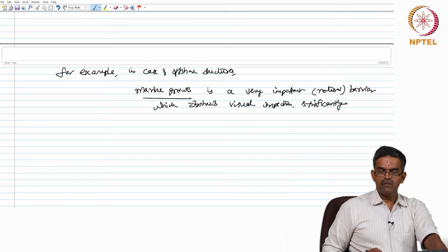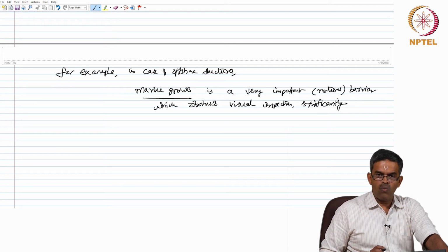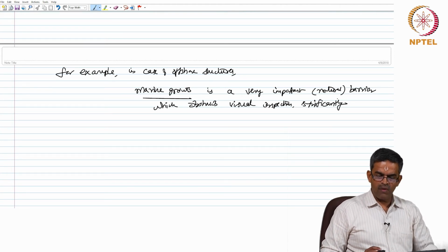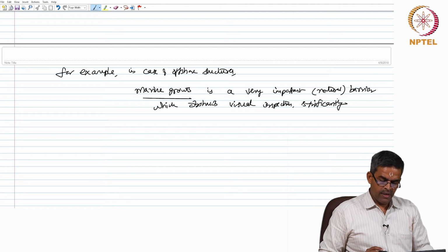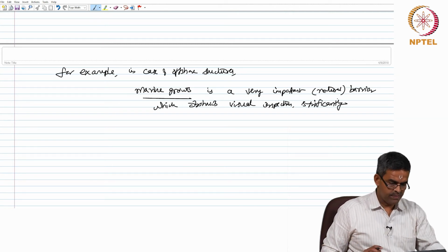In fact, the legs will be covered with marine growth, and therefore, you will not know the condition of these members under the marine deposits along the legs of the platforms. So, visual inspection has one major demerit: it is applicable only when the deficiencies are accessible.